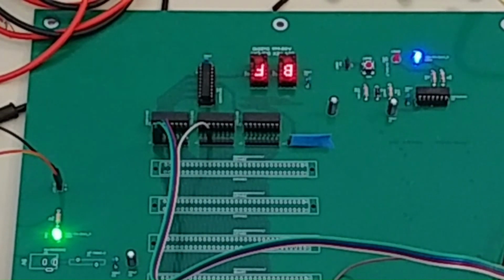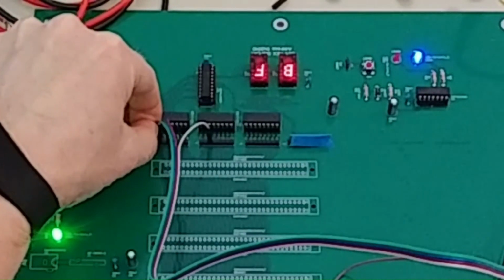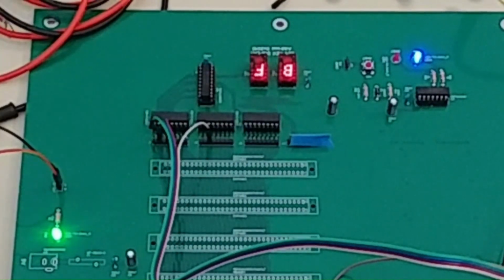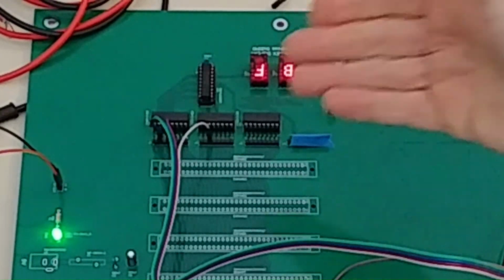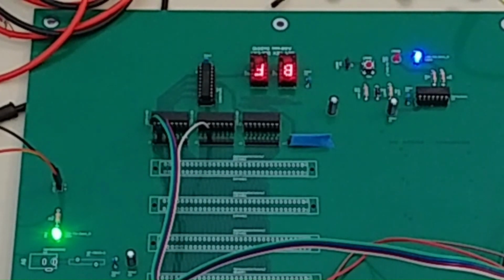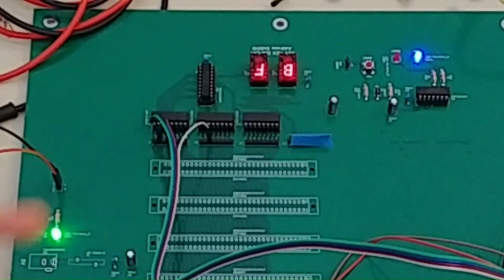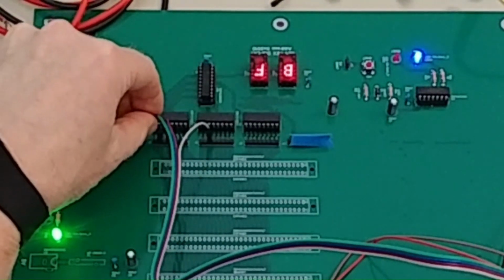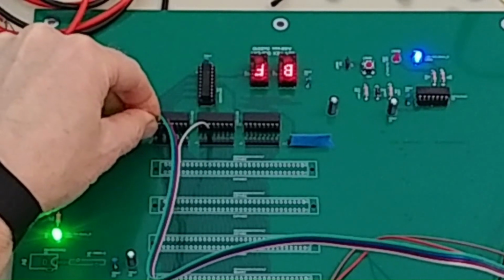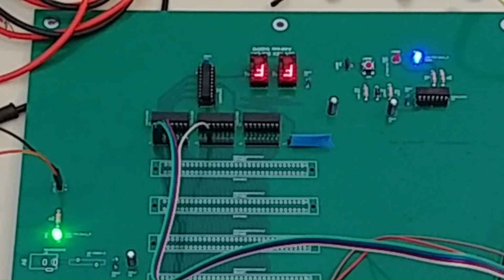Okay, and then what we can do here, as another test, is I'm going to take out A15. So we're no longer matching the 2010 on the address line. And I'm going to bring the U clock back high. So the data bus right now has FF on it, but you can see that that's not being clocked in because our address has been changed. And we'll put this back to 2010, and we see that the FF got clocked in.